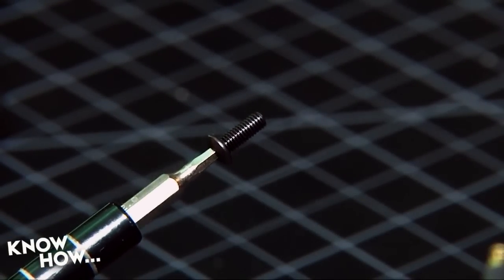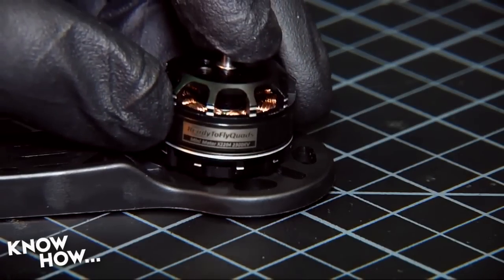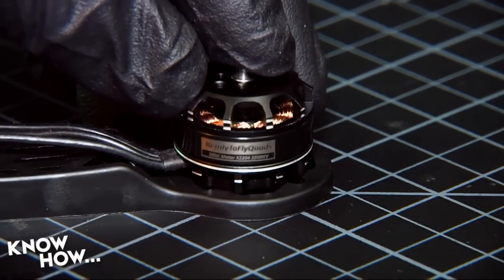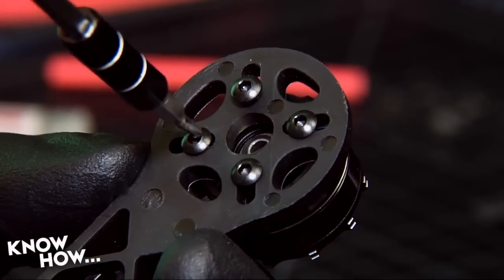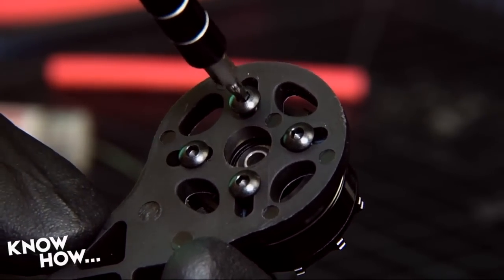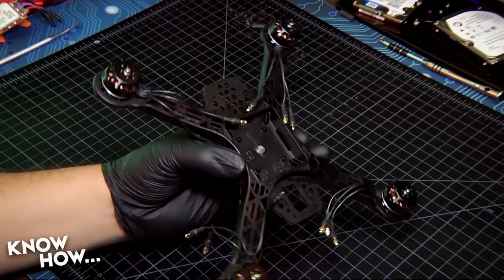Your Diatone kit comes with an abundance of M3 8mm screws. Using 16 of them to attach the motors to each arm, 4 per motor, make sure to angle the wiring harness towards the center of the frame. Dab the ends of each screw into Loctite glue to make sure it doesn't vibrate loose, and be sure to use 8mm screws. Anything shorter may not secure the motor, and anything longer runs the risk of making contact with the windings, destroying the motor.